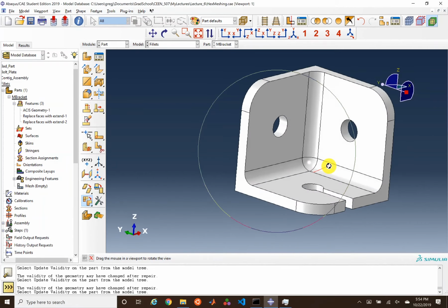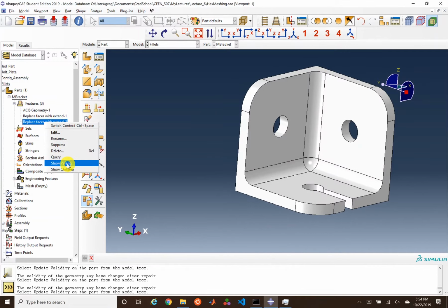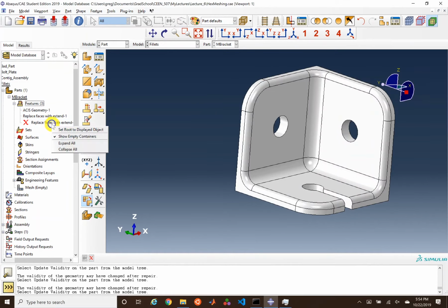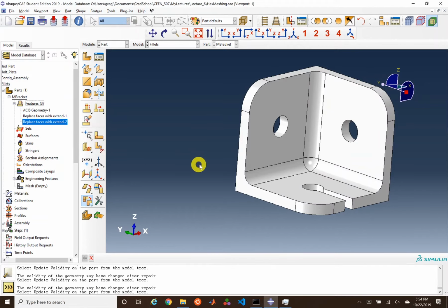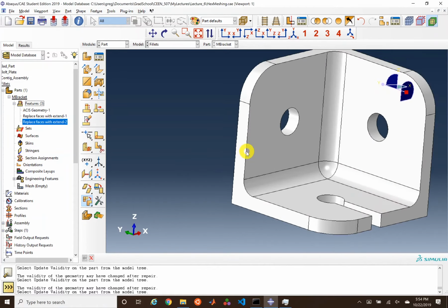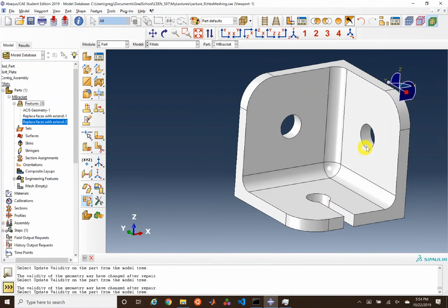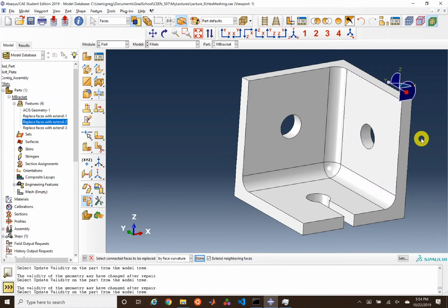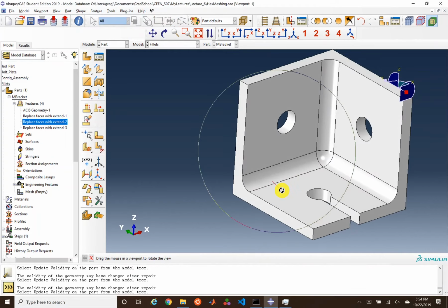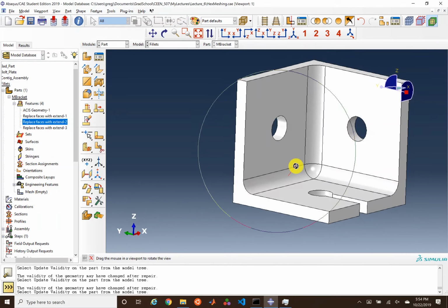So now here's a model where we can see that I've really not changed that much, just to flop back and forth. I've really only removed a little bit of the model geometry that's far away from the part of bending, and it's not really going to have much of an influence on the bending results. I could also choose to remove these exterior fillets as well. And so this is maybe now okay for me to be able to predict the overall deflection.